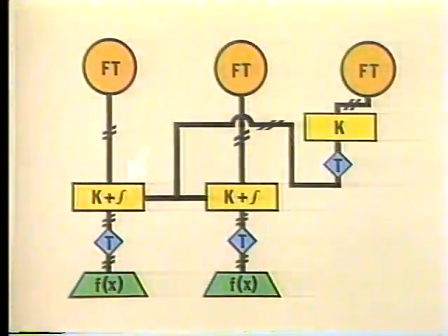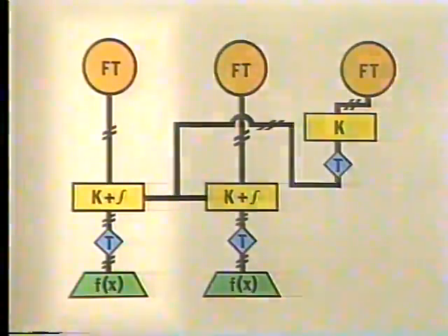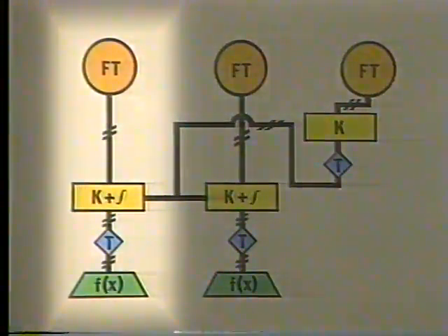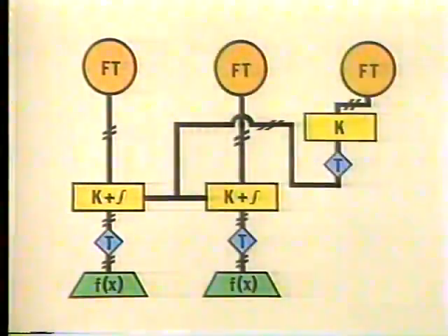As you can see, this is a PI controller. A PI controller is used in the fuel flow control system because the amount of fuel entering the furnace is critical, and fuel flow must be maintained at set point. As we've seen, a PI controller repeats its output signal until the process variable returns to set point.